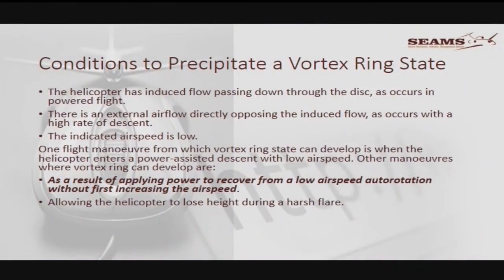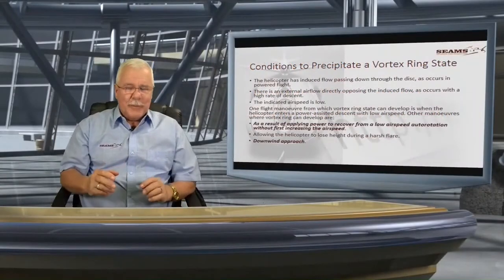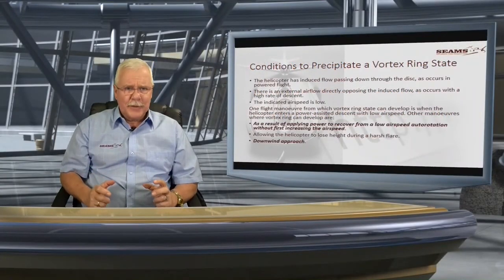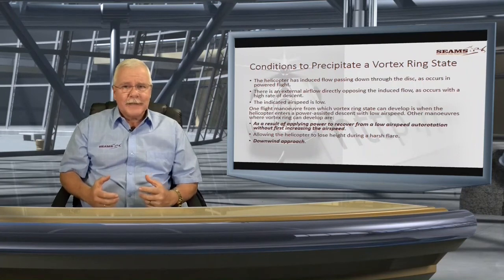All right, allowing the helicopter to lose height during a harsh flare. Now, remember when you're doing a quick stop, that's harsh flare country. Downwind approach. And you would say to me, but who would be so silly as to do a downwind approach? Guys, helicopters are real working tools.